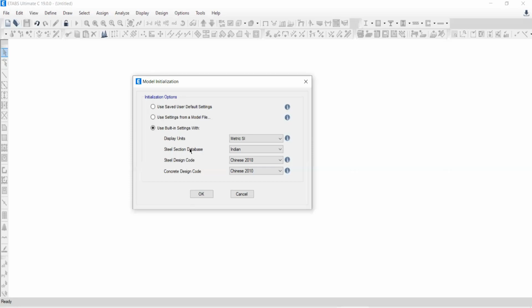So all the definitions of steel sections: I section, channel section, L section, T sections. What are the different dimensions? Suppose I am telling ISMB 250, all the standard section sizes of ISMB 250 will be available in the ETABS software itself. You have to define the country for which you would like to consider the steel section database.